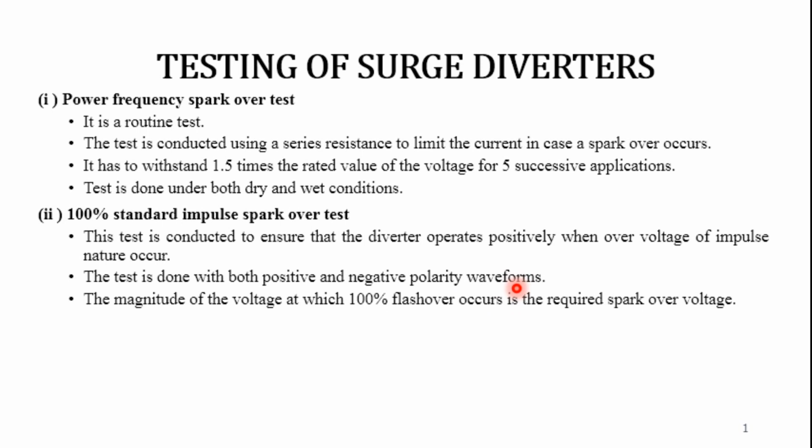Sometimes the test is done by starting at a voltage level that does not give any flashover at all, and repeating it in increasing steps of voltage till 100% flashover occurs at the required spark over voltage.